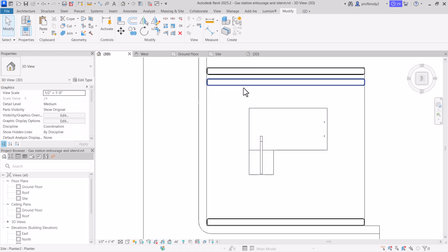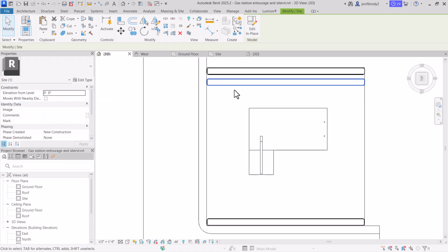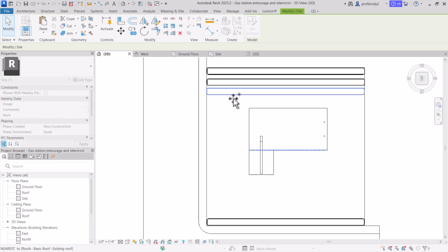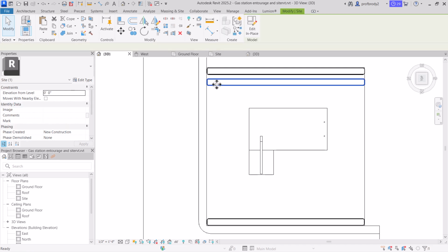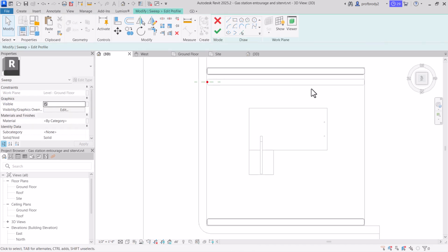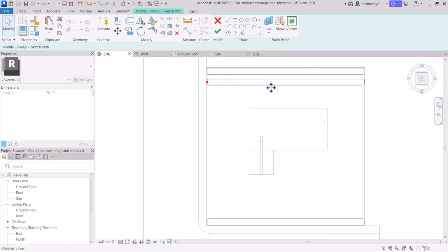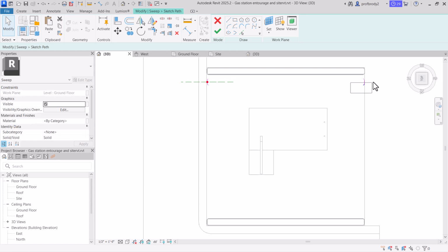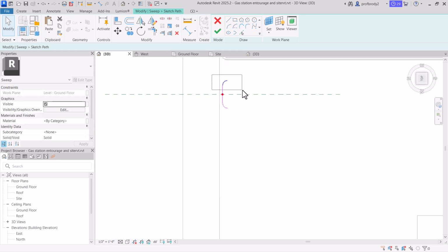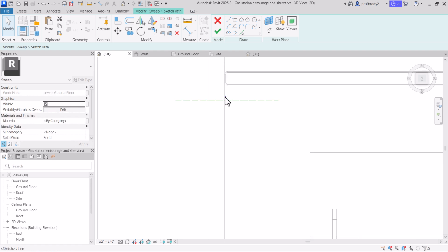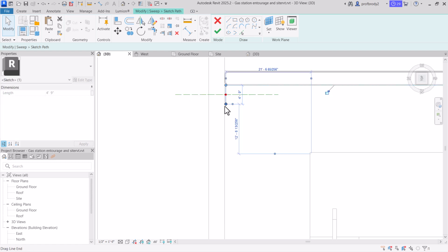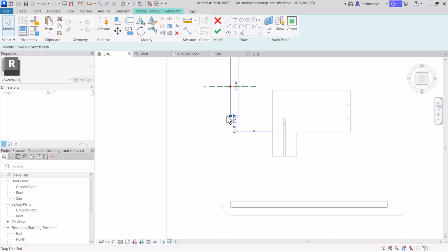And I click the copy tool. You can also hold down the control key and click and drag, and that makes a copy of an element too. So you can quickly make copies of elements, and I'm just going to keep double clicking on this until I get to the path. Oops. There we go. We've got the purple path, and I'm going to delete most of it. Just delete these guys. And if I remember correctly, the profile is on this segment. So you can't delete that segment, but you absolutely can delete everything else.